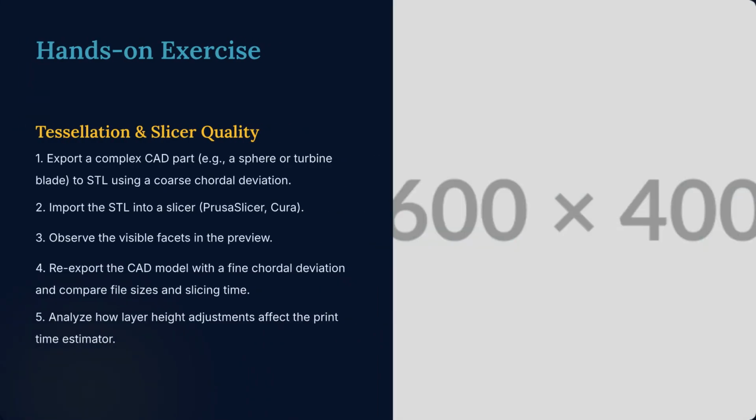For a hands-on exercise, try exporting a complex part with different chordal deviations. Import them into your slicer to observe the effects on faceting and build time.